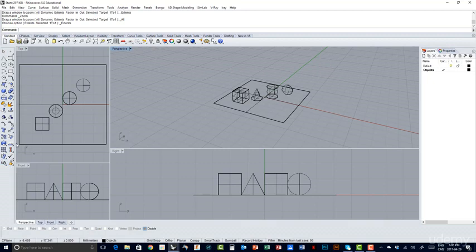So this is your main toolbar where you're going to start doing all the 2D sketches, creating your surfaces, your solids, and modifying those surfaces by using all these toolbars. You don't need to worry about these tabs. These tabs are just if you want to work on a specific function. For example, if I want to focus on just drafting and I want to dimension everything, I just select my drafting tab and that's all. But like I said, don't worry about all these little tabs. It's going to lead you to a bit of confusion when you're starting from the beginning.